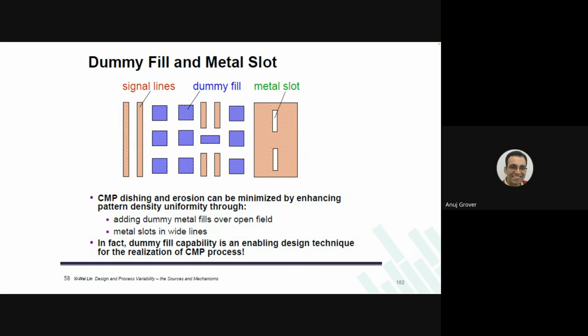See, if I were allowed to increase the metal width, then I would not have added one more extra column and I would have saved area. Yes. But it's being penny wise, pound foolish. The variations that it would introduce can result in yield loss. So whatever you saved, whatever minimal area you saved, you lost in terms of yield. So as memory designers, if matching is required, no compromises.